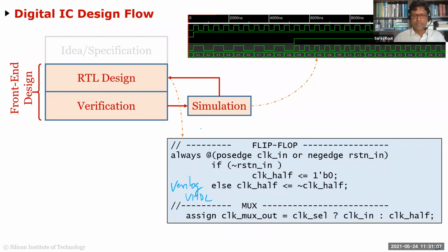That's all. So these simulators are called event driven simulators, unlike SPICE, which actually solves your entire equation, your models, your everything to basically solve currents and node equations in your circuits, right? So here they don't care about your circuit or anything. It's just saying that at this point there is an event, this node goes from 0 to 1, this node goes from 1 to 0 at certain time steps, a certain time delay, and so on, right? So it's purely an event driven simulation.